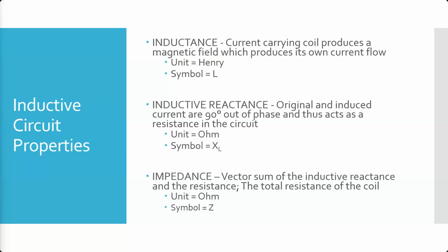And then the other thing that's going to happen is that magnetic field that's causing the inductance in the first place, when it's near anything metal, is also going to create currents in that material. Those currents in the material are then going to act back on the coil again. And those currents are the eddy currents. That is the basis for eddy current testing.